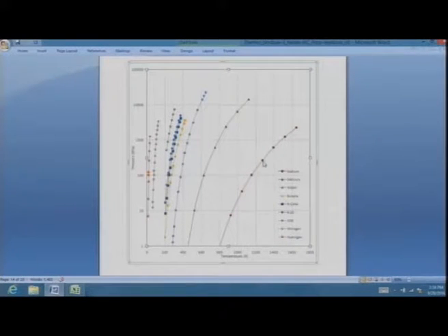If the pressure is increased, it does the same thing. So all these substances are basically showing us the same thing, that you increase the pressure, the saturation temperature increases, or vice versa, and this behavior ends at the critical point for all substances. So we'll now look at a few more charts to tell you that this is not just the case with materials like these. And one would ask, why are you bothered about sodium?